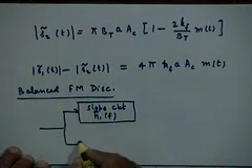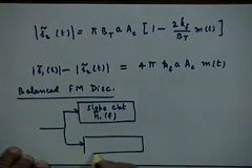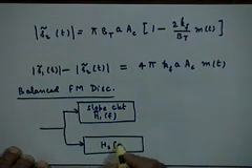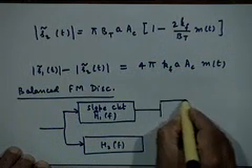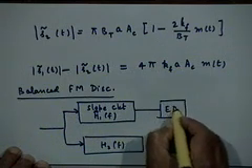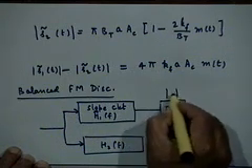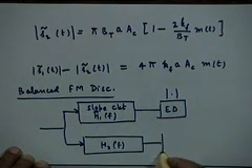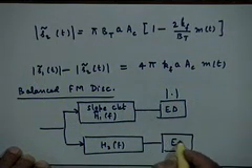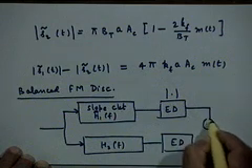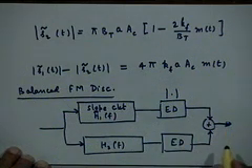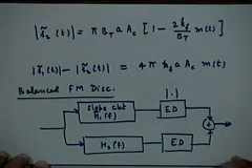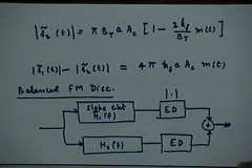We need a second slope circuit h2f. We follow them up with envelope detectors, basically a modulus operation, right, and subtract the two outputs, right. So that is the mathematical theory behind a balanced discriminator.